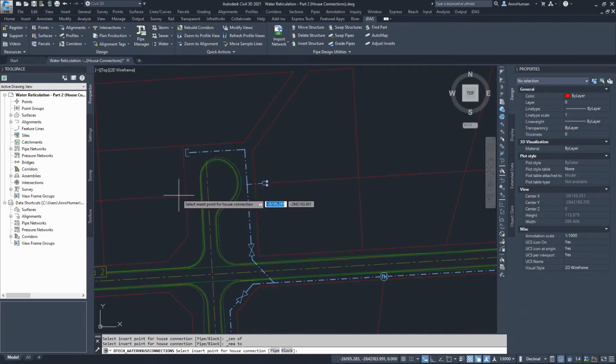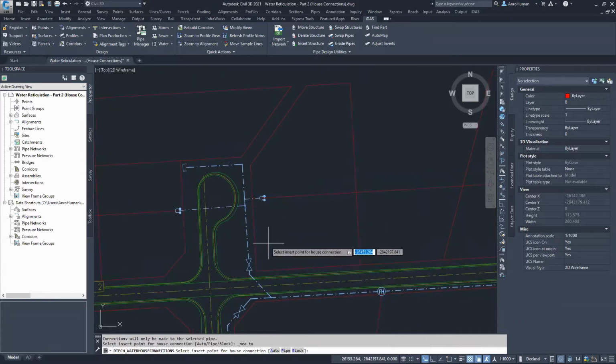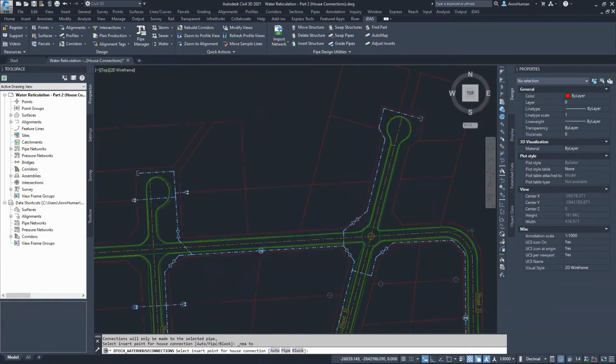And then you will see that it does go to the closest pipe. So I can promise you now, if I add one here, it's going to snap to my end cap there. And I don't want that, right? So what if I want to target a specific pipe? Well, then in this command I can select pipe. I will select the target pipe there, and then snap here. Right, I will show you how to adjust the rotation of these parts. Now I can go back to automatic.